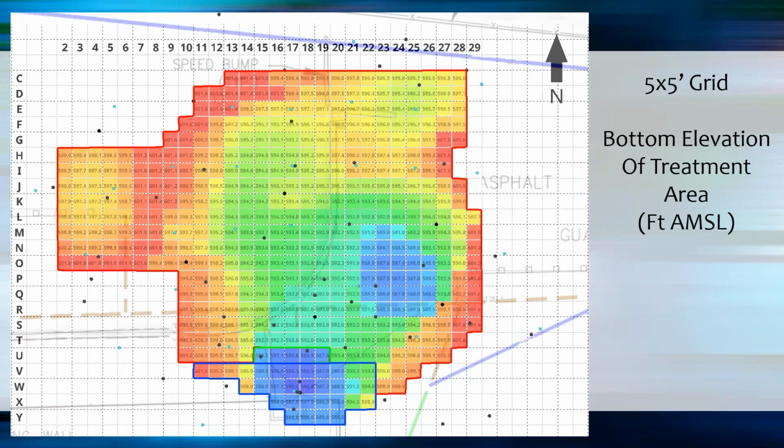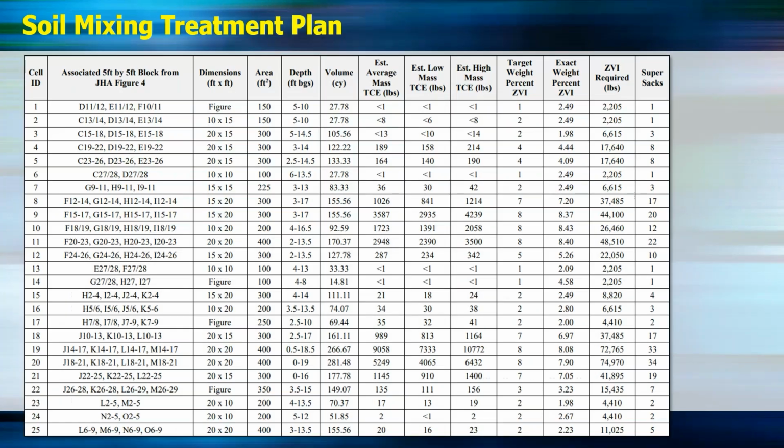The company that did this was Redox Tech, and they did a fantastic job for us. On the mixer, they actually had a GPS unit, so they weren't guessing how far the mixing head was down. They could tell, to the tenth of a foot, how deep that mixing head was and when they knew they were completed.